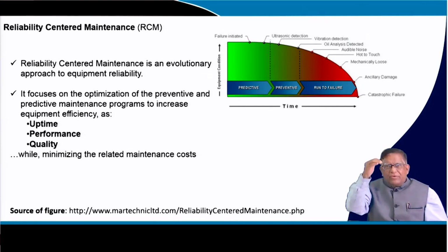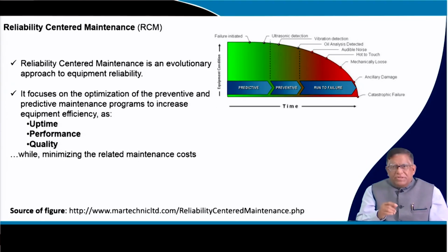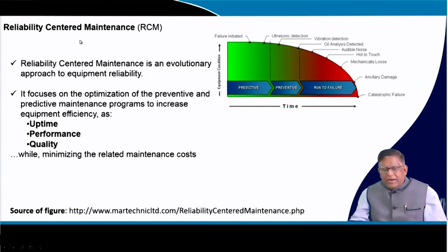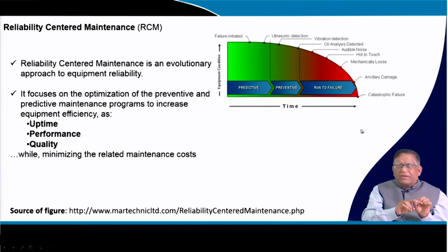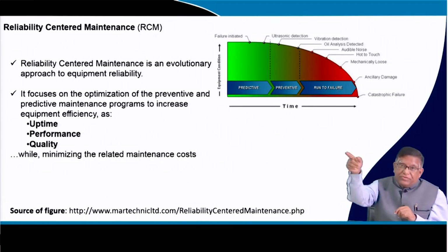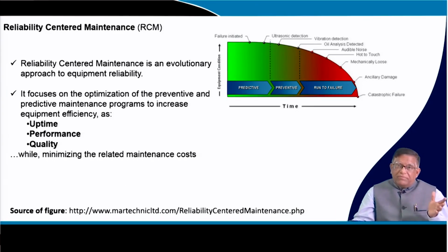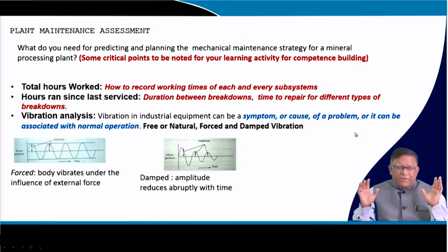For that they calculate the statistics of the whole machine, how it is working, and different key indicators. In predictive maintenance they calculate from ultrasonic detection, vibration detection and all the parameters they collect. On the basis of that they can calculate whether the machine will still give me the performance one month from now.